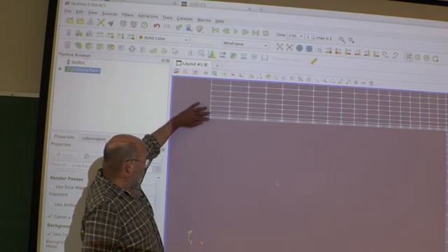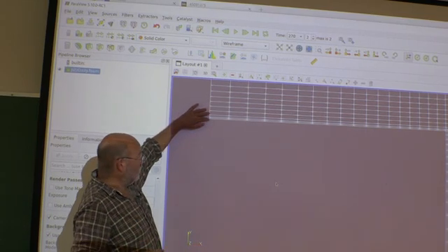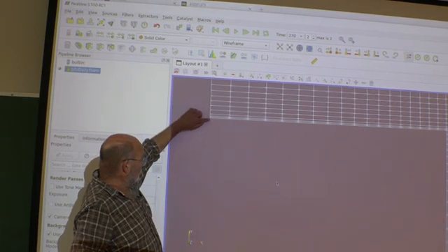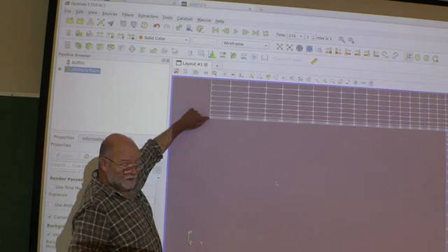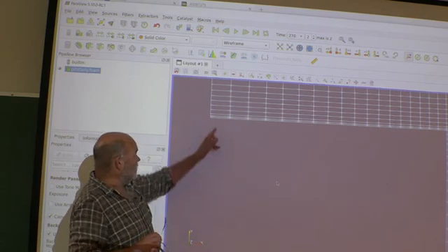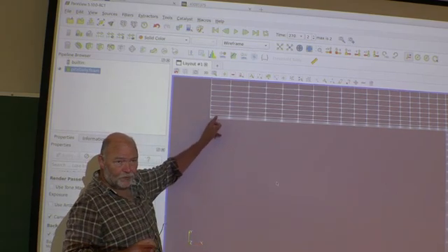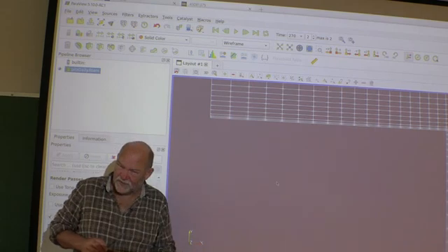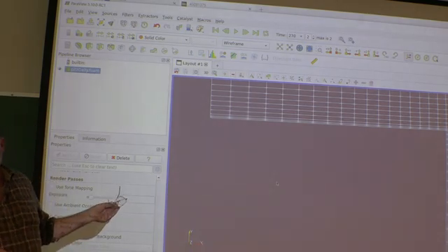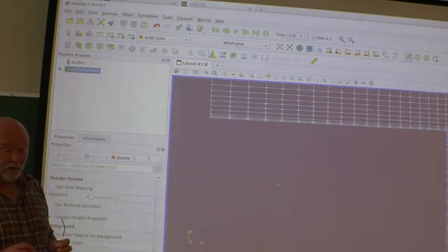First cell, closest to the wall, that was the first time, split in half. Then I did it again, so the next one also split in half. Little bit crude. Here you have, say, 100% change in area. That's not so good. So it's a very crude method, but I mean it's cheap, and sometimes it can save the day.